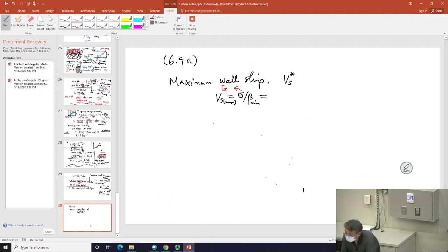The plateau modulus, just for completeness, is something that you learn from small-amplitude oscillatory shear measurement. By doing that measurement, you get G double prime and G prime, and there will be a crossover frequency, which is about the reciprocal relaxation time.